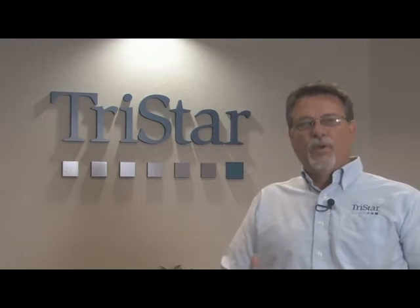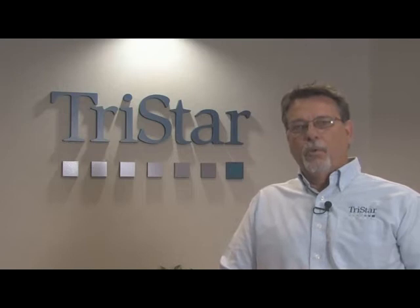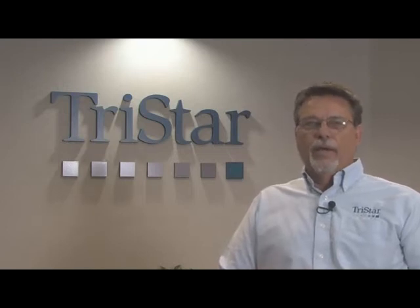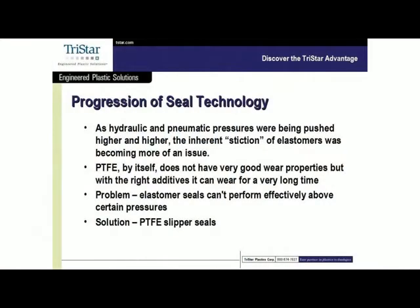As pressures continue to go up, there are some applications where an O-ring and a backup ring or two backup rings are perfectly adequate for design. But it was out of that advent of PTFE as an anti-extrusion ring that a whole new family of seal technology came into being called slipper seals.